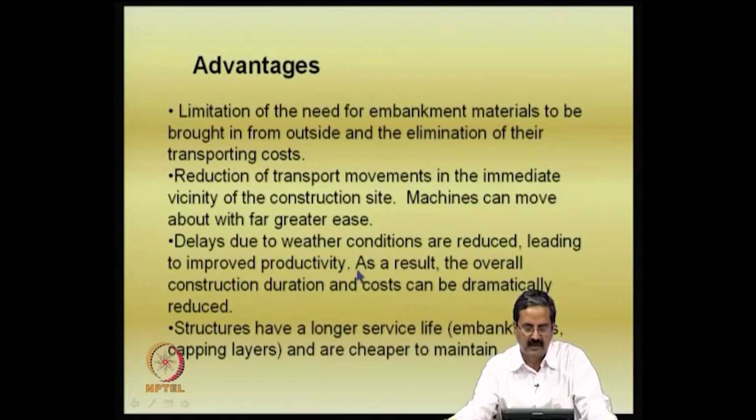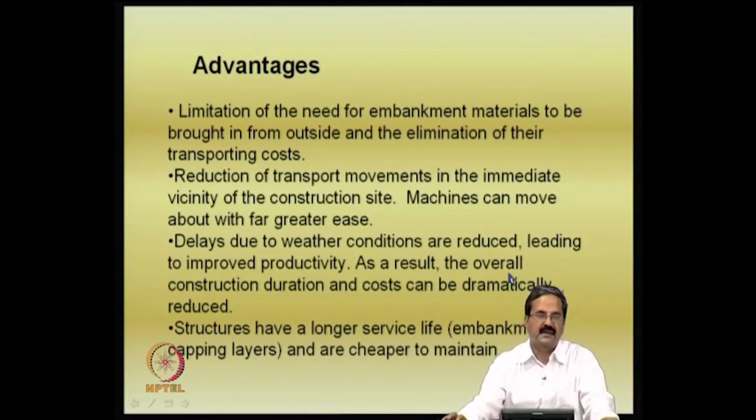In fact, this is another important variable. If the weather conditions are very poor, like in a rainy season, there is not much change in the water content, and water removal is not easy. In a rainy season you want to remove the water, but it is not that easy. If you add lime at that stage, one can overcome weather conditions and treat that soil area.